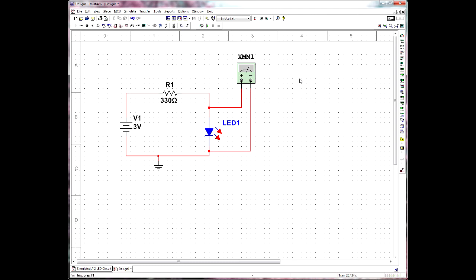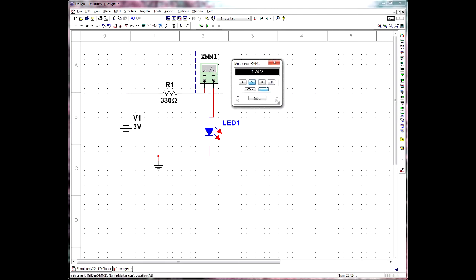Now we'd like to take the reading of the current of this simple circuit, so we'll have to modify it as follows. We have to insert the multimeter in series after the resistor but before the LED. So we add the points like so. Now the multimeter is inside the circuit, and we can correctly take a reading of the current. The reading we're getting is 3.819 milliamps.